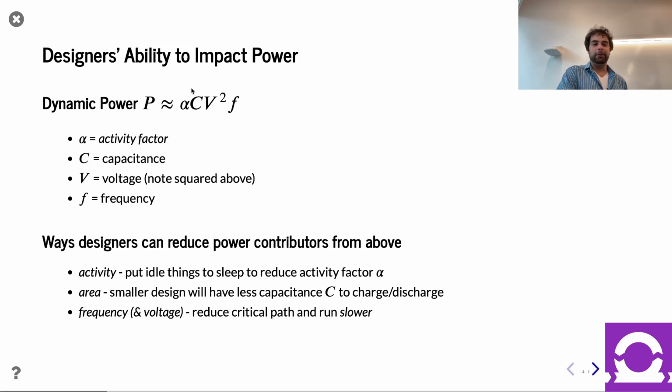So how might one derive this? The class schema is something like, we take an inverter and model the capacitance on the inverter, and this model goes from 0 to 1, 1 to 0, the charging and discharging of that capacitor, right? Basically, when we think of our circuits more physically, we have our wires, transistors, etc., being put together to build our logic gates and memories and registers.